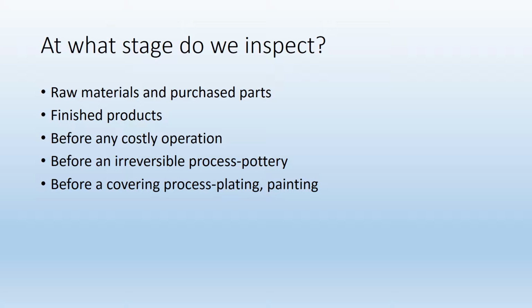At what stage do we inspect? Raw materials and purchased parts, finished products, before any costly operation, before an irreversible process such as pottery, and before a covering process such as plating and painting.